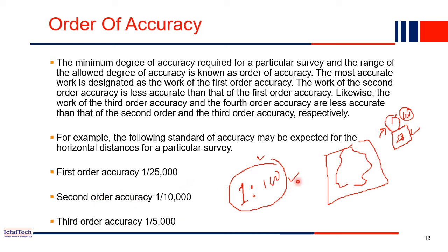So depending on the type of survey, which survey we are doing at a field level, I mean country level or a plot level, depending on that, we have to choose the appropriate accuracy level, the standard given by the government, and from there we have to make the reading. So if the accuracy is very low for the plot level or the small scale level, we should reject those readings. You have to retake the readings in the field.